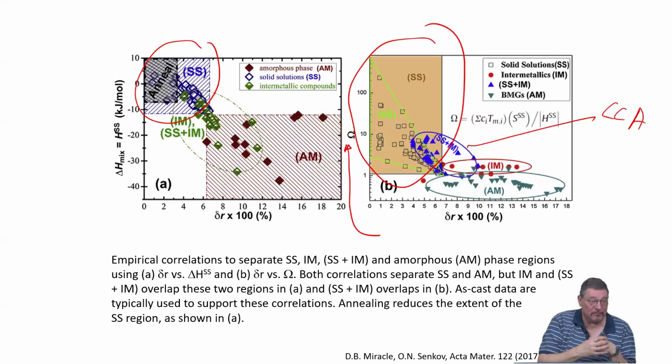You will still miss maybe some of the intermetallic phases, but they would probably have very complex or rather complex crystal structures, because then you need larger elementary cells, and this is computationally more costly, so people avoid doing that. But they would also form much slower, so the probability that these form is lower. So I mean, if you first start with an experimentally informed database for CALPHAD, and then you calculate based on these phases which should exist, it's, I think, a very good start.